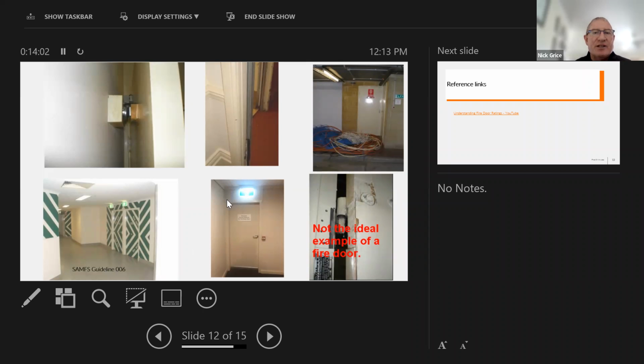This one's here in the hotel I recently stayed in. Quite fine. It's got the emergency exit light. You've got your fire door there. You know it's no use having a lock or key. One pushing action down, one action and pushing the door open, you get to the emergency exit. I'd always recommend when you go to a hotel that you check that door opens.